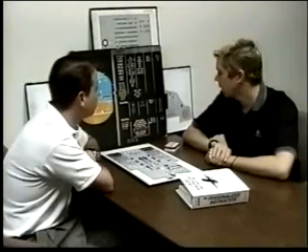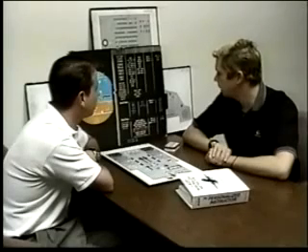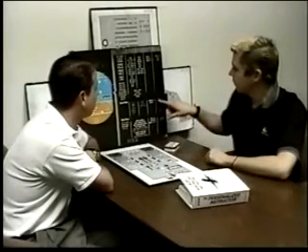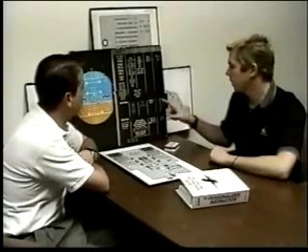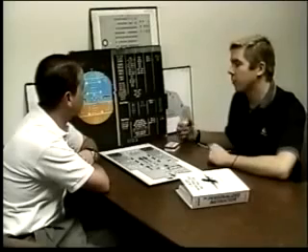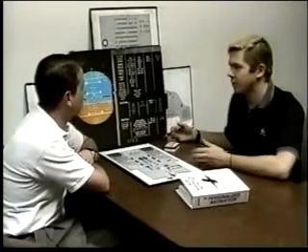Is there ever a scenario that you wouldn't see...? Yeah, you couldn't see 2 FD1. The reason for that is, if they're both on and they're both operative, the captain's going to get number 1, and the first officer is going to get number 2, and you can't force it any other way. So if they're both available, both on, 1 FD2. If you had 2 FD1, that would indicate that they're both on, the captain's got number 2, and the first officer's got number 1, and that just can't happen.